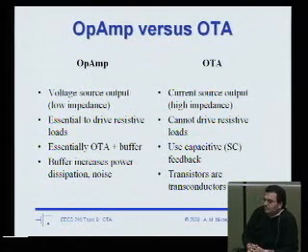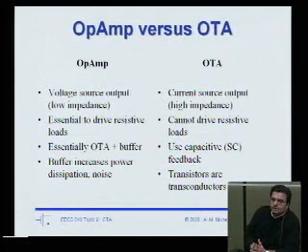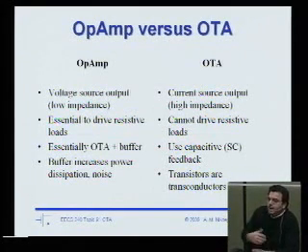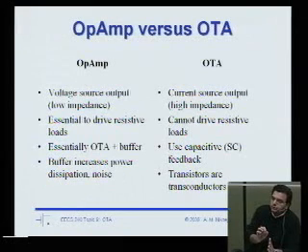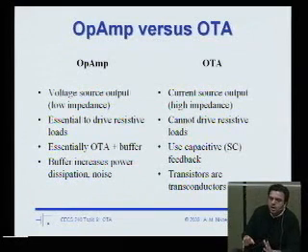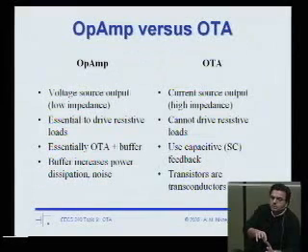Well, if I'm designing an op-amp, what is the main ingredient of an op-amp? What do I really need out of an op-amp? Right? I need a lot of gain. Op-amps have a humongous amount of gain. So if op-amps didn't have buffers and I put a resistive load at the output, the gain would just drop down to a very low value, right? Because the way we build an op-amp with an OTA is there's an internal point that has very high impedance, so that our gm times capital R is huge. So that buffer is actually to protect that high impedance node.